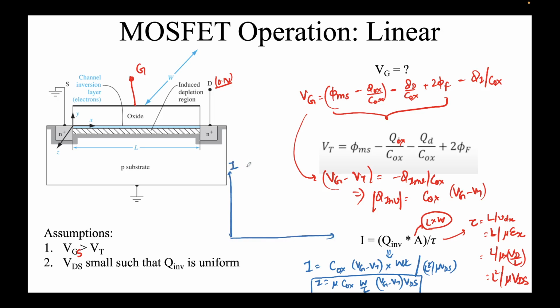Now let's try to plot how it looks. This is ID, also known as IDS, versus VDS, right? Because these are the two terminals across which I'll plot, and remember, gate voltage is the knob. I told you, the barrier which increases or decreases, right? ID versus VDS is the output characteristics, like when you draw I versus V of a resistor, right? So how does it look? I versus VDS is a straight line, right? Let's draw this. It's a straight line for a given value of Vg.